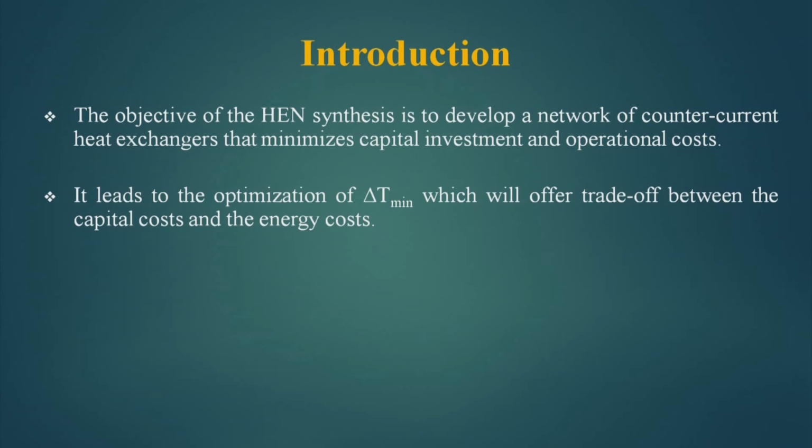To know this, the cost targeting is necessary, because when we design the heat exchanger networks, we have to target its cost, that is capital cost and operational cost, and we will select that heat exchanger network which will have minimum. It leads to the optimization of delta T minimum, which will offer a trade off between the capital cost and the energy cost. It needs a lot of discussion.